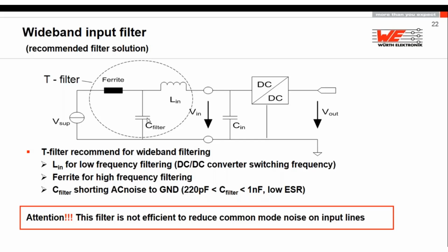But for this ferrite bead, you should not use the super duper 2.2 kilo ohm one, the most powerful, or 2.7 kilo ohm. It makes no sense. All these 2 kilo ohm ferrites have a peak of 2 kilo ohm, but because they are multilayer, with many layers inside, they will not have a nice bandwidth. Additionally, all the ferrites are measured in a 50 ohm system impedance. We don't have 50 ohm system impedance in a DC-DC converter. We may have something between 10 and 20 ohm system impedance.